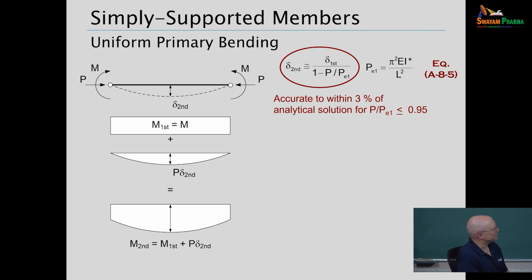So we're just looking at the aspect of the axial force P. If we make a cut at some location along the member in the deformed configuration, then we need some additional moment for equilibrium, in this case P times that delta, at that particular cross-section where we're making the cut, or relative to the reference axis at that cross-section.